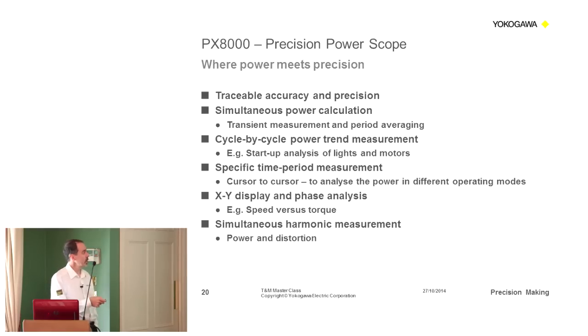So that means that we can do cycle by cycle and choose which part of your waveforms you measure the power. So if you've got varying power, for instance, if it's a process, I've mentioned a printer, for instance, or even a microwave, which basically has power on, power off periods, you can bring up your cursors and measure power of particular parts. And of course, this is something you can't do with a traditional averaging type power meter.